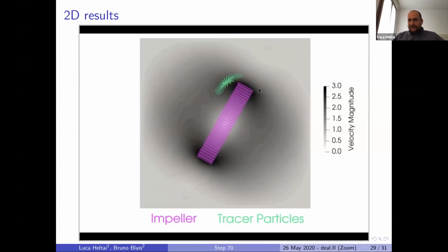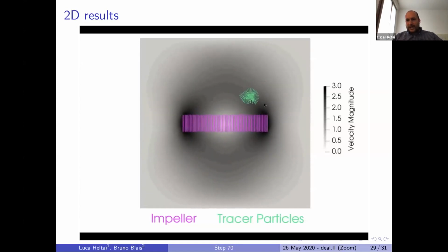It's not exactly identical to the initial position. And we track 2 different particles in the solid. One are passive tracers, and we use exactly the same technique that we use for the solid tracers. And one are the solid particles, which we move ourselves with something given from the outside. The velocity of the fluid is just imposed using penalization parameters on the fluid. And as you see, the resulting blur is, of course, because it's only a first order scheme, so we should have higher order schemes in this case to get better conservation properties.